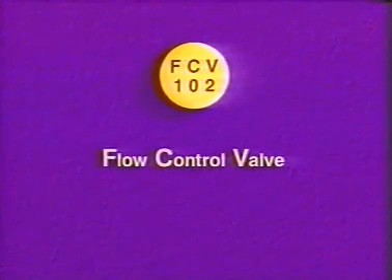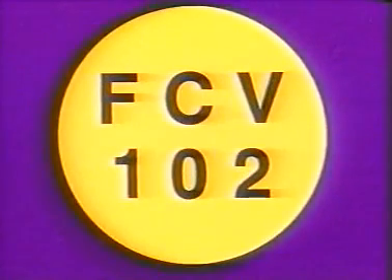Valves that are part of an automatic control loop are called control valves, and the letter C is always the middle letter in the valve symbol. Let's review the location of indicating letters. The letter for the process variable is always first. If the instrument indicates, records, or performs some other function, or if the device is a control valve, there should be a middle letter to indicate this. Last, there's a letter that stands for the actual name or function of the instrument.